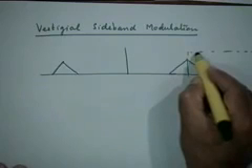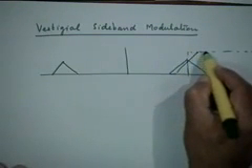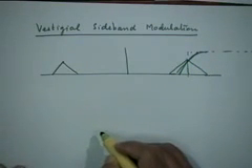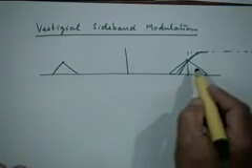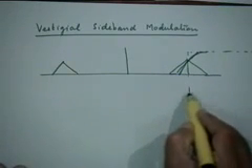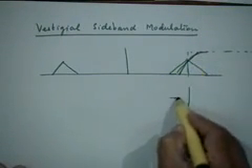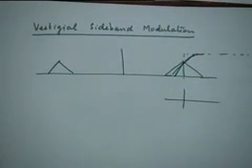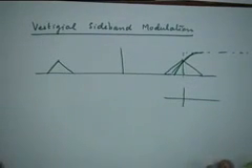Typically what will tend to happen is that even if it is a good filter, it might be like that as far as amplitude characteristics are concerned, and the phase characteristics perhaps in this area would be highly nonlinear, because the sharper the cutoff, the more nonlinear it tends to become. So phase characteristics will tend to become highly nonlinear, which will imply some kind of delay distortion or phase distortion of the low frequency components of the message signal.